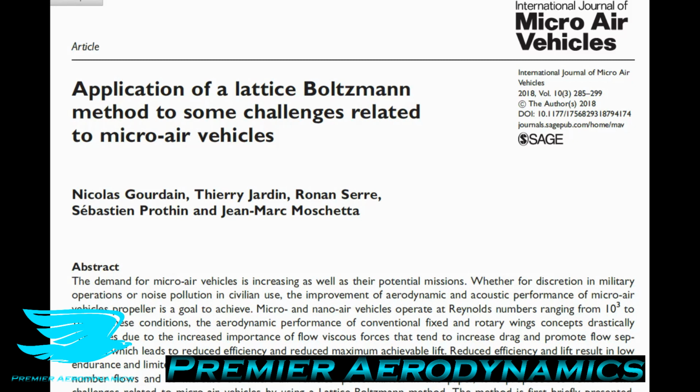The reason is because the way that the simulation is set up is that it divides these cells up. So each core is working on different cells, but there has to be communication of the information of these cells between the two cores. So you calculate, let's say, group A with core 1 and group B with core 2, and group A might have all these different pressures and velocities and turbulence and whatever you're calculating. And some of the cells in group B might need that information. So you need to transfer this information. So you might have a 40% reduction in computational time instead of 50%, as you might want.